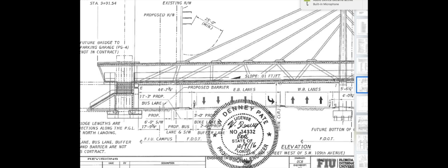So to get a crack here, if we move both of these together in unison, imagine both of them moving in unison, because all of these truss plates or nodes, blister bars, all locking in like a truss plate, steel plate. If the bridge were to sag a little bit, we'd have the action of this no longer being plumb on each end because it's sagging in. We'd have a hinged little location on the bottom here where it would rock out, if you will, and you have some clearance at the bottom of this.